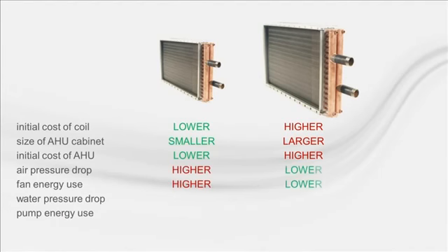A larger air handler will typically result in the lower air pressure drop through its components, which can reduce fan energy. And because the coil is also part of the chilled water system, its geometry contributes to the water pressure drop. A larger coil will typically result in a lower pressure drop. Finally, the extent to which the coil raises the leaving water temperature can dramatically affect both the installed cost of piping and pumping energy. And coil performance can even influence the efficiency of the water chiller.